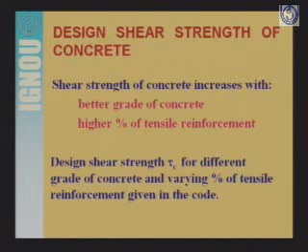First is grade of concrete, and second is percentage or the amount of tensile reinforcement provided. And based on these two factors, the code specifies the values of the design shear strength for concrete.